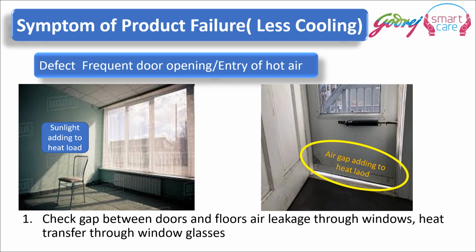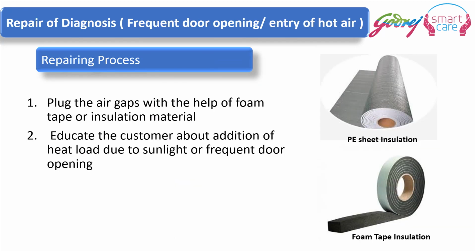In case of frequent door opening and entry of hot air, we have to check the gap between the doors and floors, air leakage through windows, and heat transfer through window glasses. We have to plug the air gaps with the help of foam tape or insulation tape. We have to educate the customer about the addition of heat load due to sunlight or frequent door opening.